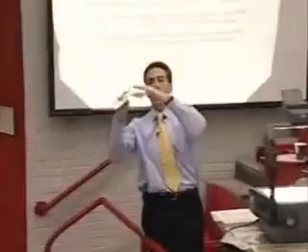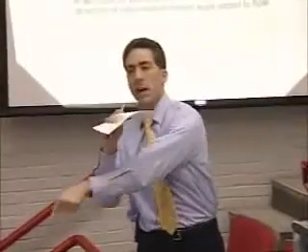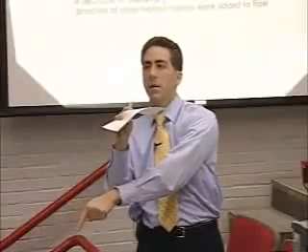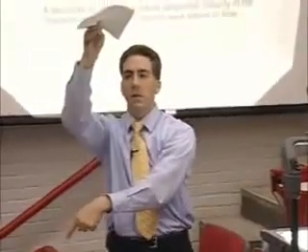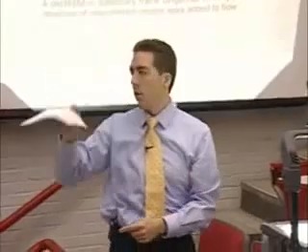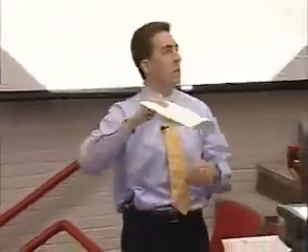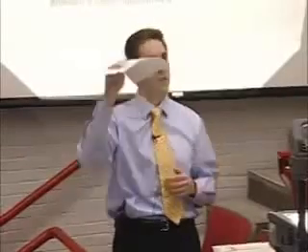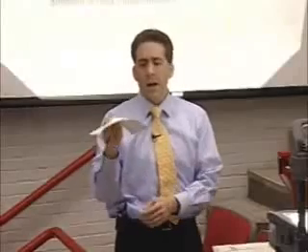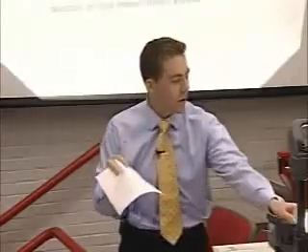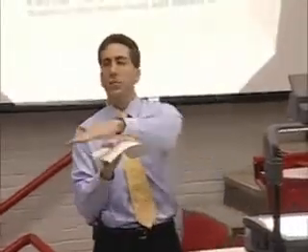So if this is my stall, someone mentioned, if this is my blade and the flow is coming in, it will tend to stick to this blade and head off in that direction. That's what produces the lift. I've got momentum coming in like this. I put the momentum down like that. I must get a force opposite to it. All right, so airfoils, and these are just spinning airfoils, change the direction of the flow, and that produces the forces. The only time that this does not hold is if you have stall and the flow separates from the blade.